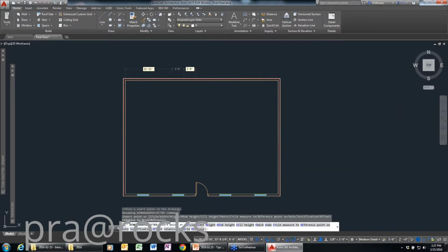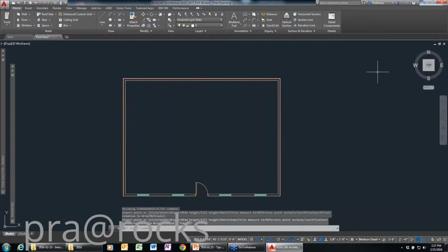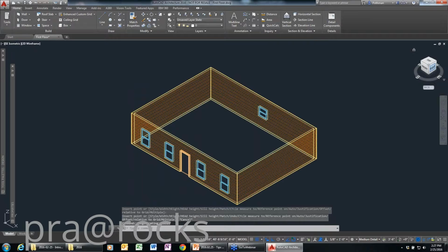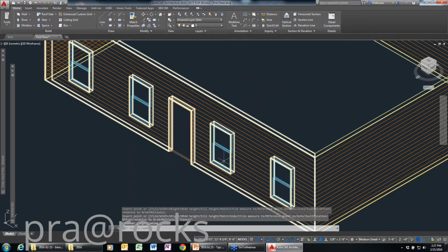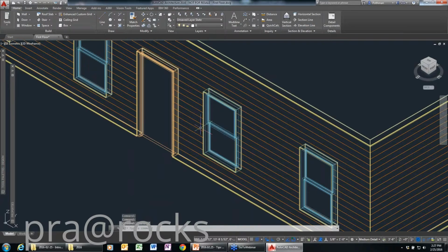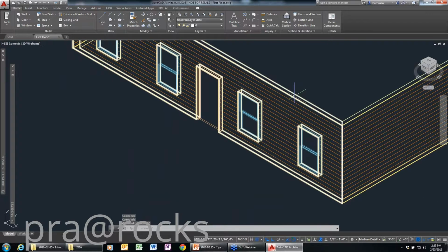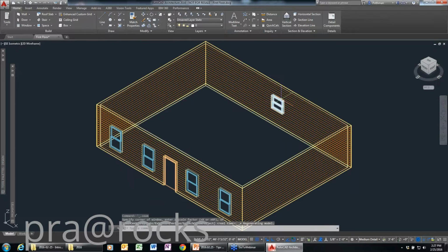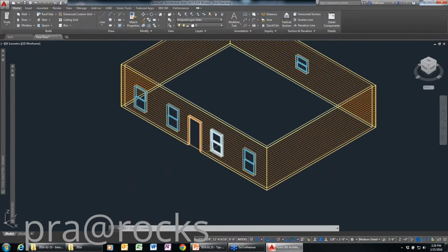And let me see, if I just flip to a viewpoint here, you'll see that now I've got my double hung windows, which are probably flipped around backwards. Should be the top panel on the outside, but again, swapping something like that is just hit the flip grip and you can fix the panels there. But then I have my 3 foot window, which has the same head height, but it's only 3 feet high instead of 5 feet high. So very quickly I'm starting to lay out a very simple design, and certainly AutoCAD Architecture does a lot more than residential design.